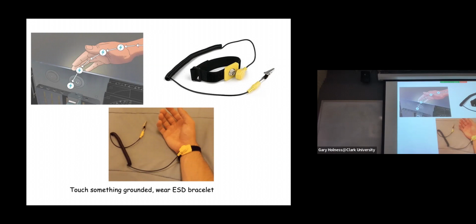And so what you do then, before you interact with a circuit, is ground yourself, right? You want to find something typically metallic that is connected to ground, like your computer has a voltage and it's connected to ground. So maybe you touch part of the metal on your computer to make sure that you haven't built up static charge, right? Because you can kill a chip by zapping it with static electricity, and you never intended to do so. Okay? All right, any questions?